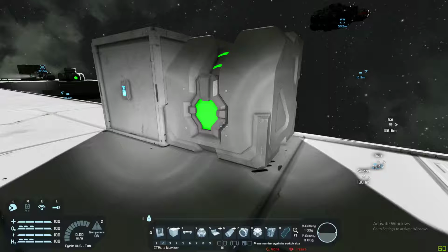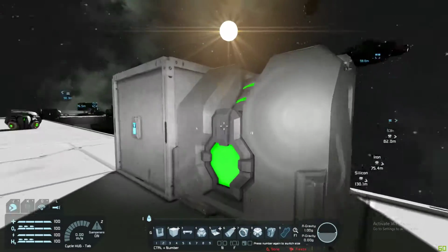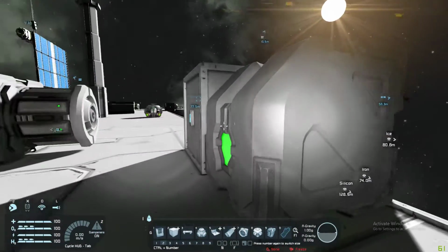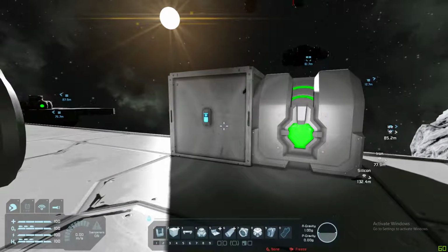So your controls will be completely the wrong way round. When you try and tell it to fly to a certain place, if the remote control block's the wrong way round and it's done on autopilot, it won't be aligned correctly and so on. So always make sure you align this block with the green eye pointing forward, and the slope also is a secondary indicator.